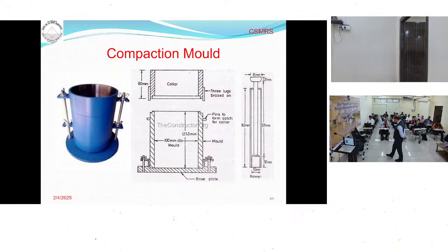Basically, when you talk about the soil particles, they have interparticle friction and interparticle locking. When you add the water, it reduces the friction force. So when you apply the mechanical energy, they slip to new positions. In that way, the voids are reduced.